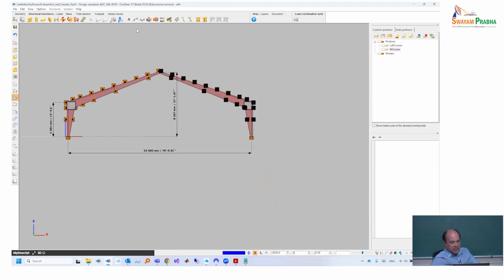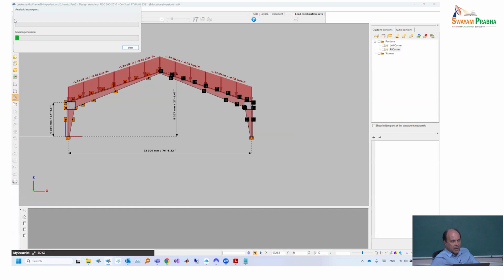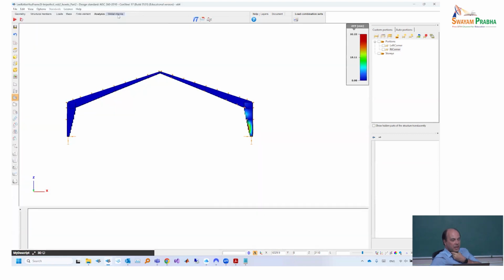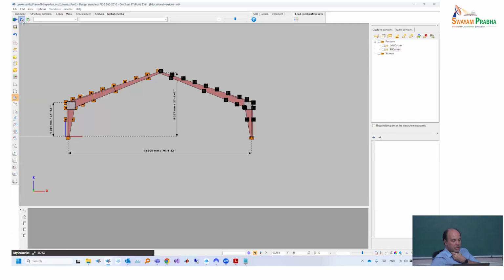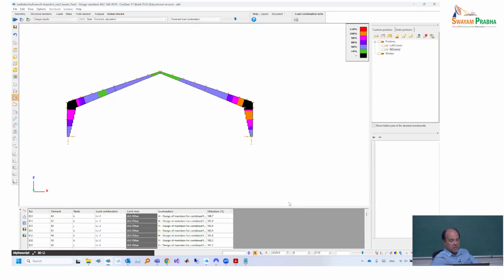So now, once we did so, let's try to give another try. Let's run the calculation again, this time with these boxes already implemented, and go back to global check. I go back again to the first buckling mode, which we know that it's not good, but let's see that maybe the situation is already a bit better because we are not checking anymore those cross sections which are in a region where we are not supposed to check. Now, from the second result, we see that that region became black.